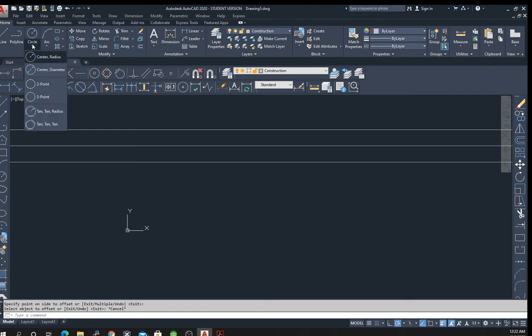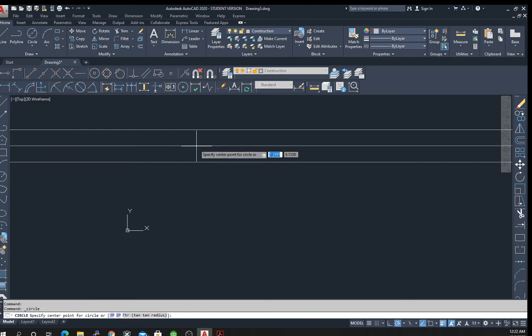We're going to choose our circle diameter, and we want to make sure that we're snapping to 2D reference points. So we want to be able to snap to something here. And yeah, we can certainly snap right here. So we said 1.5.